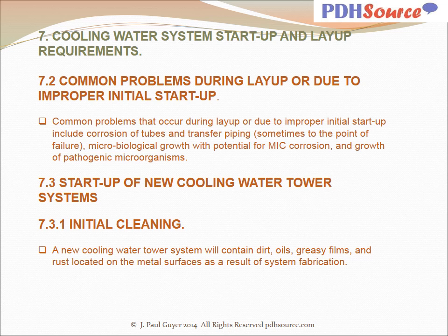Common problems that occur during layup or due to improper initial startup include corrosion of tubes and transfer piping, sometimes to the point of failure, microbiological growth with potential for MIC corrosion, and growth of pathogenic microorganisms.